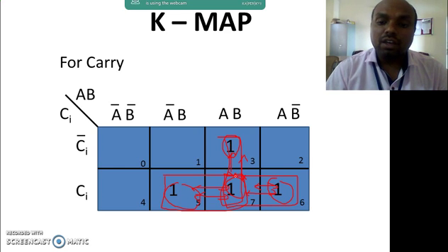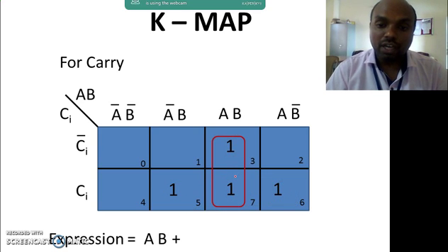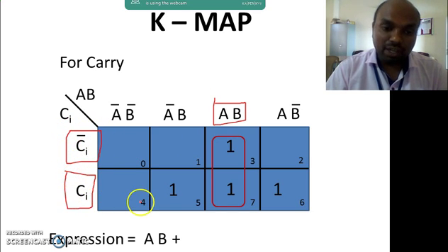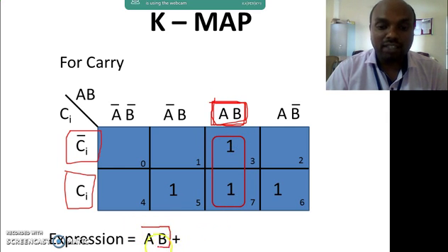You can clearly see in the K-map tutorial that is available. So here I have mapped these two. So these two are having the same similar expression as AB only. But here the third variable Ci dash and Ci varies. So these two are complement to each other and these two get cancelled. So only this AB remains. Only these two input values remain. That's why for these two, one combination, I have written the output as AB only.